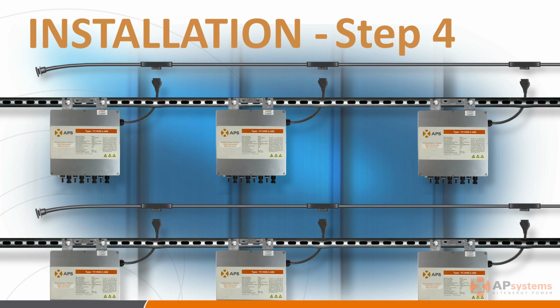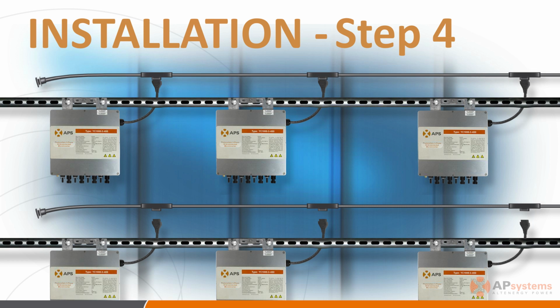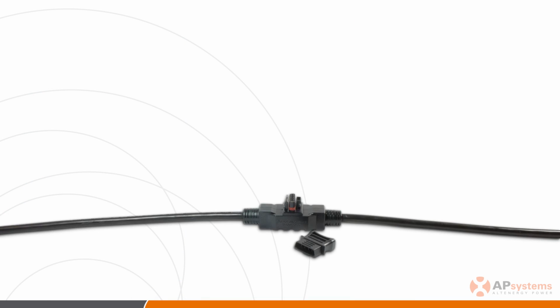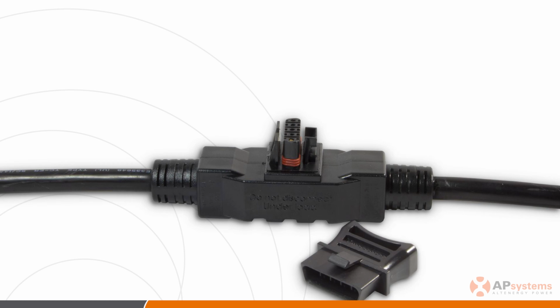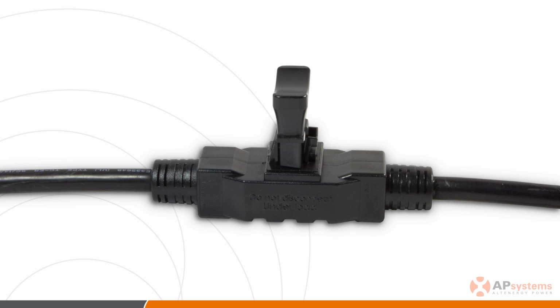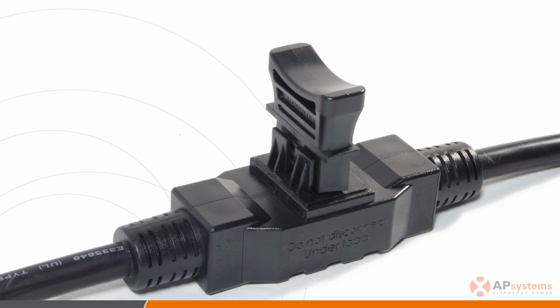Step 4. Place the modules onto the racking system and connect the AC cables from the inverters to the AC bus cable. Make sure that all unused terminal connectors on the AC bus cable are covered with T sealing caps, ensuring that they are weatherproofed.